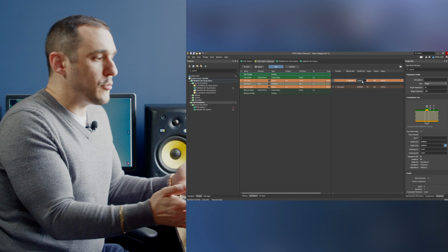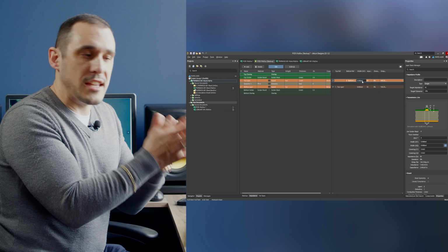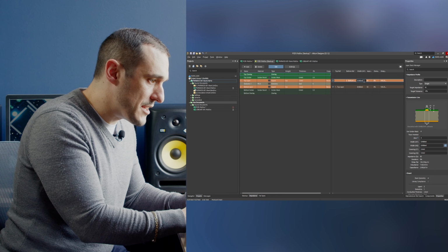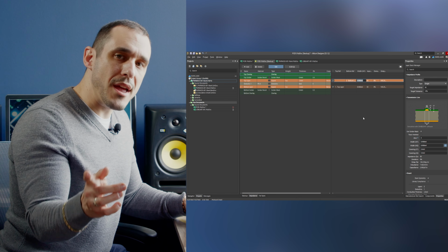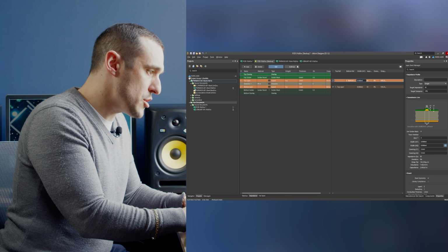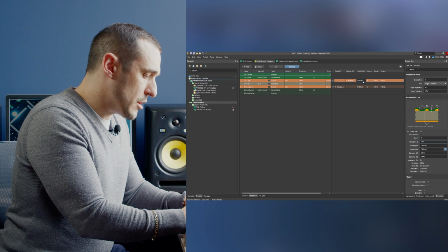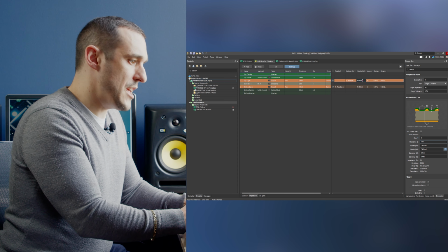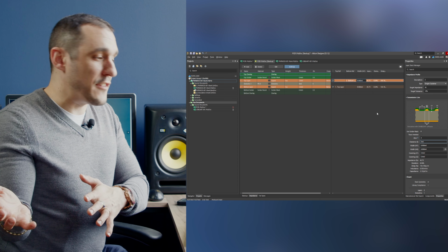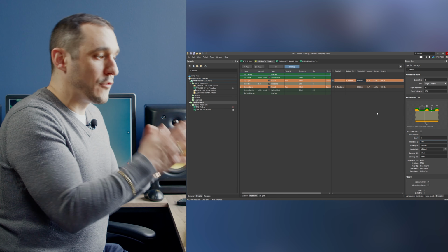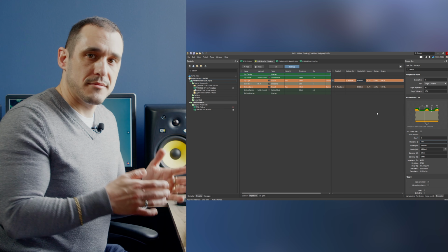Now, what would happen if we use the width that we calculated earlier, this 8.968 mil value? What would happen if we used that same width in the coplanar configuration? Well, if I take that number and I put it in here for the width in my coplanar line, you'll see here that the impedance is actually not 50 ohms, it's actually 45.73 ohms, okay?